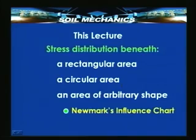Now, in today's lecture we shall proceed further and we shall see some more details of how to compute stresses beneath rectangular and circular areas, but we shall not stop only with that, we shall proceed further and see how to compute stresses beneath an area of any arbitrary shape. Now, the last one requires the use of a graphical chart which is known as Newmark's influence coefficient chart, that we shall see towards the end of this lecture.